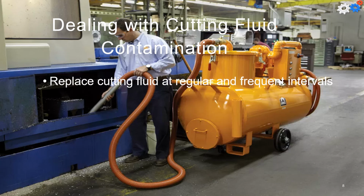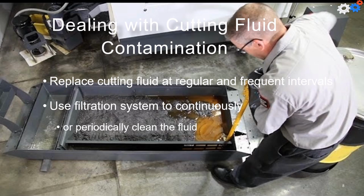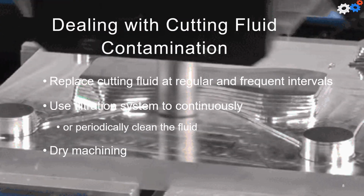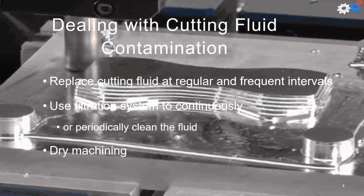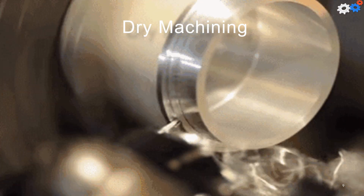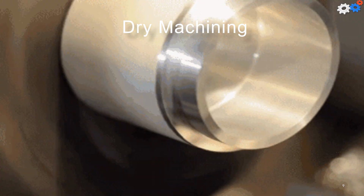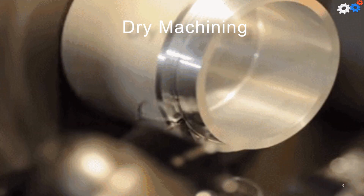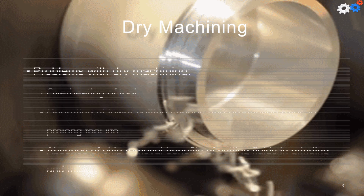You need to replace the cutting fluids at regular and frequent intervals. Also, use a filtration system to continuously or periodically clean the fluid. And finally, you can go with dry machining. In dry machining, no cutting fluid is used. This will avoid the problems of cutting fluid contamination, disposal, and filtration.